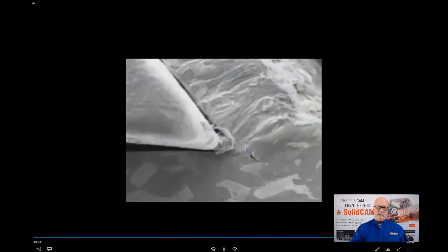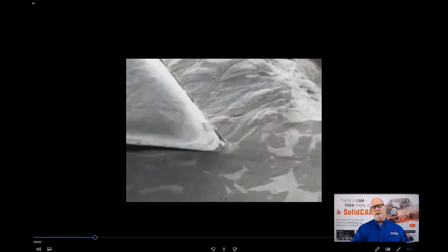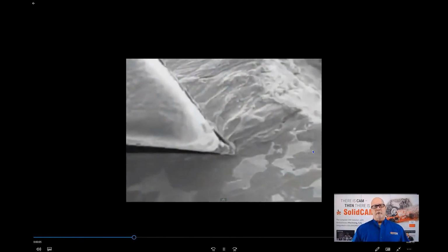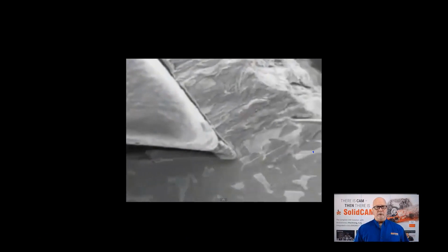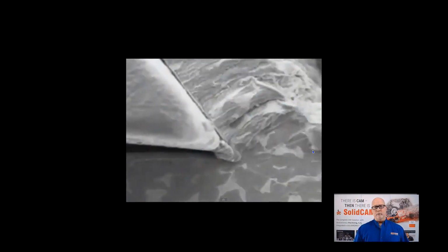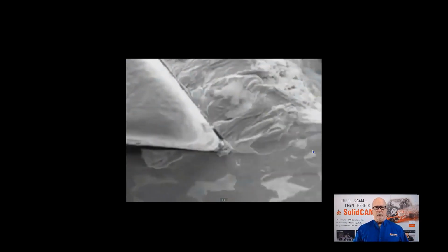What's going on along this line is called plastic deformation. This is actually a dislodging of the molecular structure and separating that material. This is the actual chip removal. Okay, really more of a chiseling effect, if you want to think about it that way.